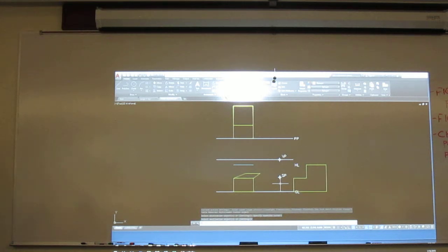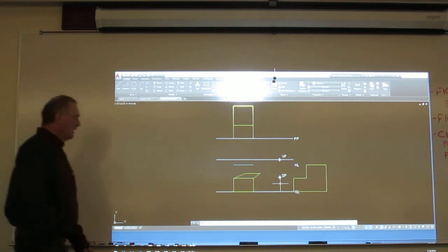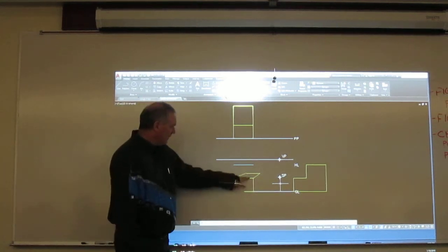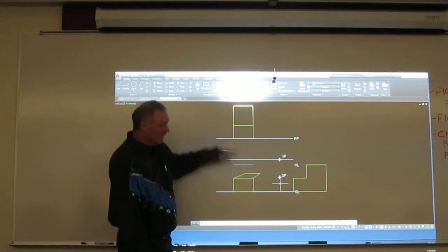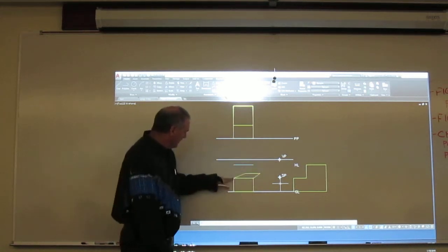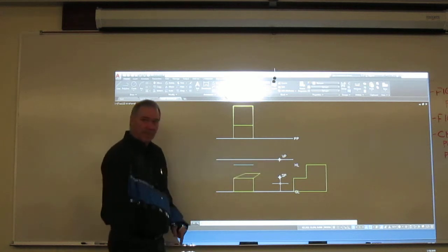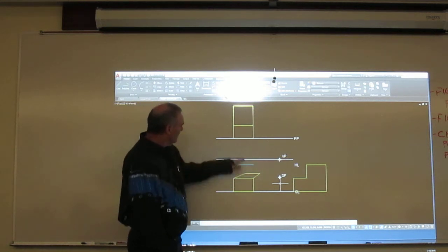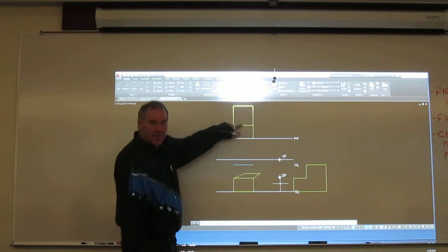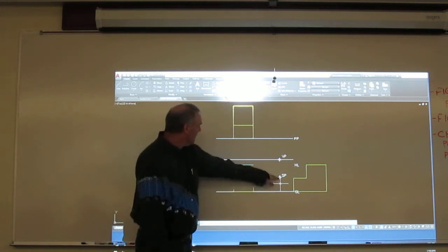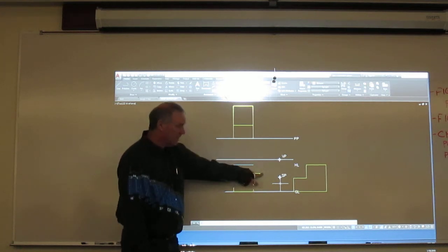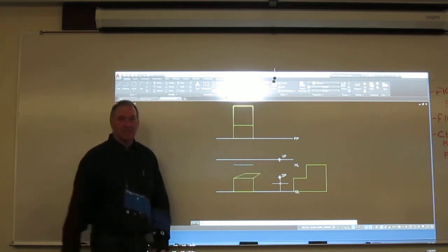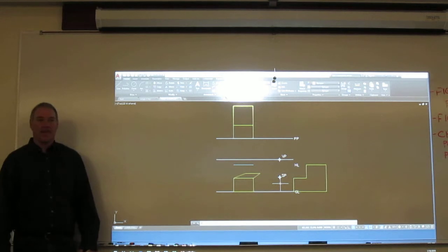Okay, I had to redraw this top. I have true size, so I know from this, because this vanishes, right? Everything on this angle. So I went from here to vanishing point, here to vanishing point. I had to locate this back edge right here. To do that, I went from station point to point, right across the picture plane, bring it down, draw a horizontal line to the other one, trim it up.